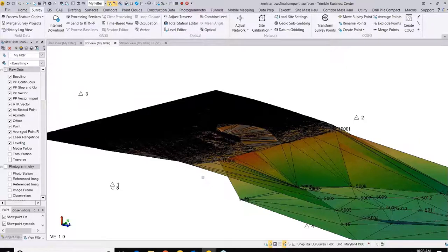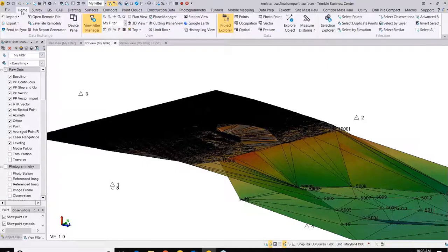Well, in the importer of TBC, when you're importing a CSV, there are custom import file options where you can ignore that top line. You can choose how many rows to ignore, and that would be the way to not import a header like that. Yeah, the way I do it with my formulas, I don't even see them in there, Chris. I'm sorry. I usually just do it a different way, and I've never had that come in. So I just take them out before I'm even in there.